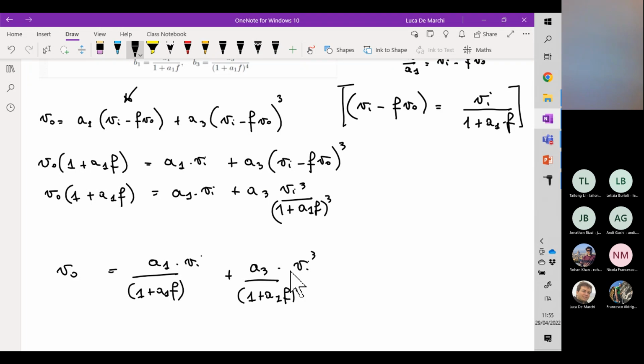And this is good news, because with respect to the original signal to noise ratio, which was Vs over Vn, now, well, this 1 over beta factor can be simplified, and we can say that the signal to noise ratio at the output is Vs over Vn times A2. So we have this amplification of the signal to noise ratio.